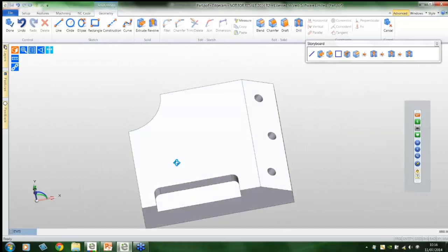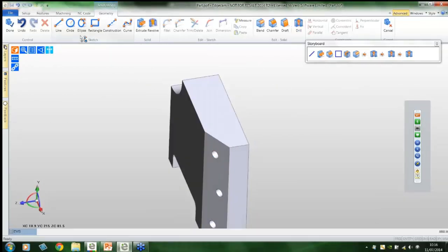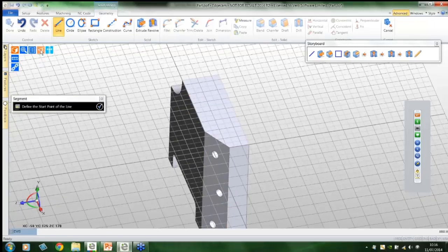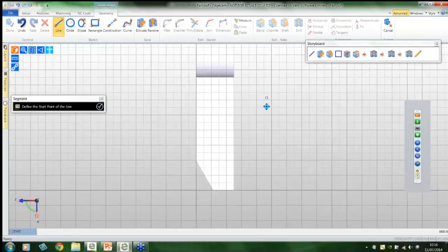So we've got some drilled holes. And again, yes, you can just draw freehand, you don't have to just draw rectangles as I tend to do, but again, as you begin to draw, the work planes will appear. Again, it's a good idea to eyeball, as I say, down on that face. But again, you're under starter's orders now to draw, so draw away. Again, I'm just going to join this together.